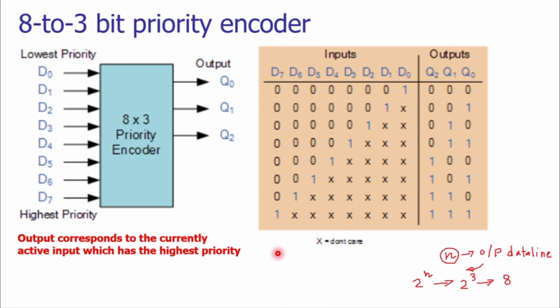So to convert the analog signal, we are taking help of the operational amplifiers, and then we are converting them into the high level signals and low level signals using comparators, and comparators in association with the encoding circuitry, we are generating the digital outputs.